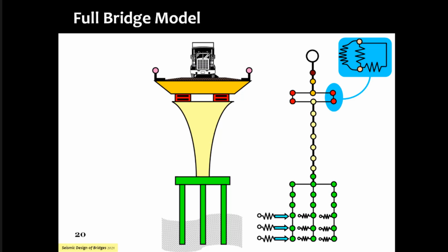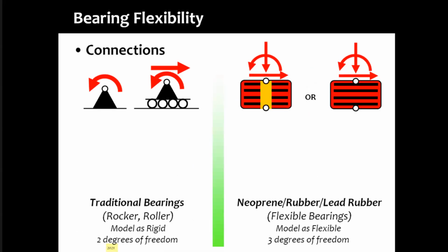Coming to the issue of bearings, you will now, from use of manufacturer specifications, arrive at what is the vertical compression stiffness, the lateral translational shear stiffness, and the rotational stiffness of the bearing along both the axes of bending in plan, the X and the Y. And then you will put that as an input into your computer analysis.